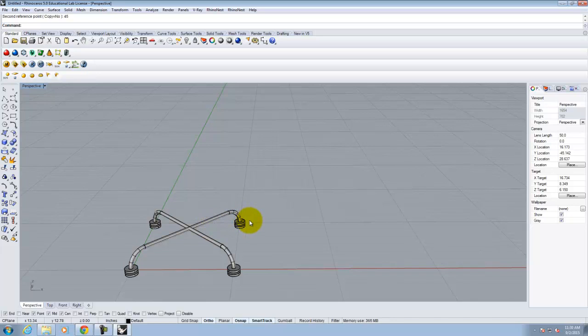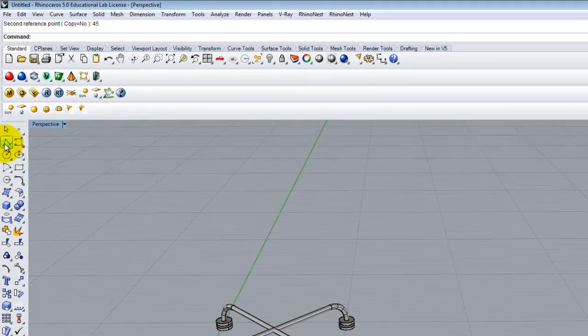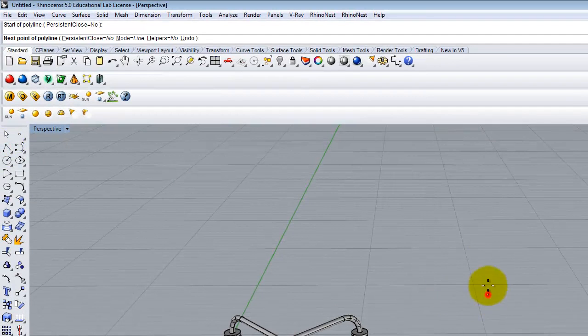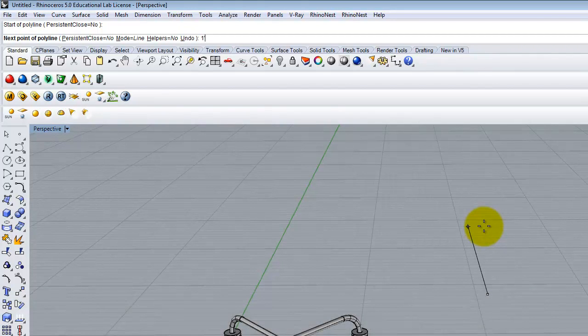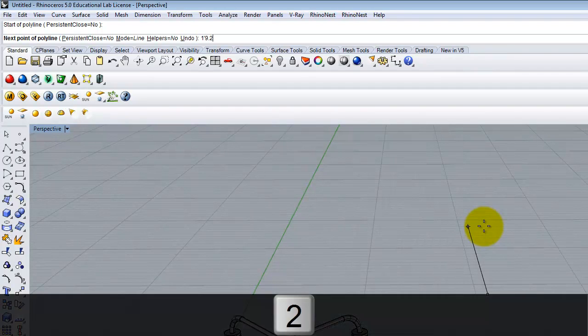Okay? So the next thing that I'm going to do, hold on, I want to make sure that I didn't skip anything. Good. There's a drawing on the back that gives us some dimensions of what this looks like. What I need is a line, and I'm going to model it over here. That is 1 foot 9 1/4. So 1 foot. Now, if you have to type in 9 1/4, that is 9.25, so I could do 1 foot 9.25 inches.